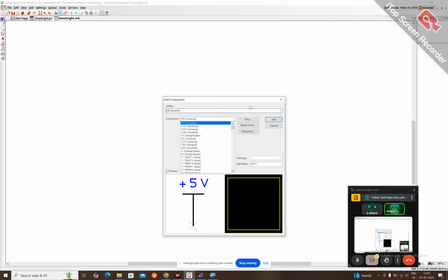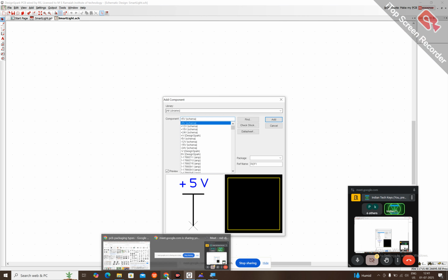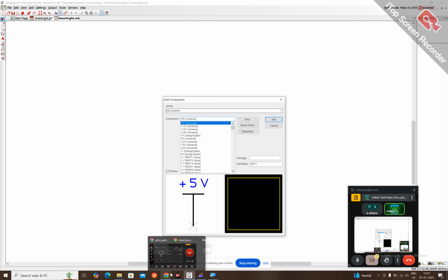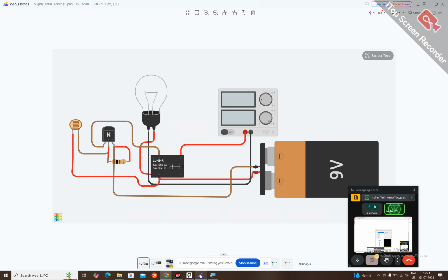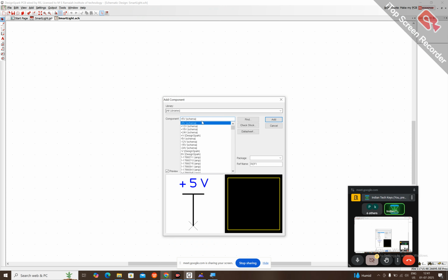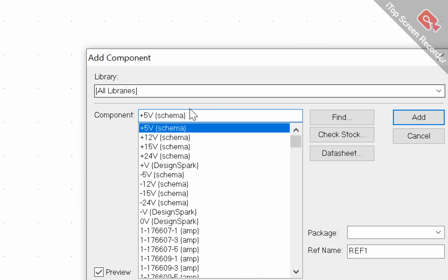So now, the first thing I want is a screw connector. I'll start from one end. I need a 2-pin screw connector for this, and for this. Okay, and let me not use a battery, guys. Instead of using the battery, I'll use a converter from 230 supply to low power. So first I will use a screw connector, a 2-pin screw connector.